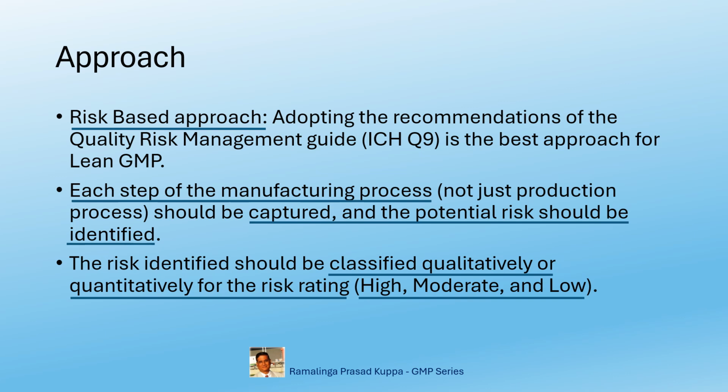For FMEA, you have qualitative reference, whereas for FMECA, it is decided based on the score. So, FMEA, when evaluated using a score for criticality, it refers to FMECA. In the FMECA word, C stands for criticality, the score obtained by multiplying the score for severity, probability, and detectability. That is the SPD cycle.